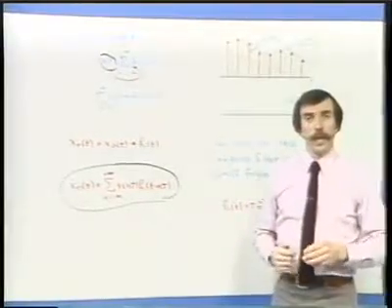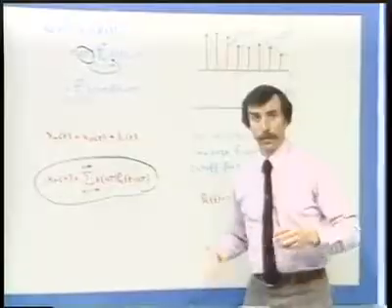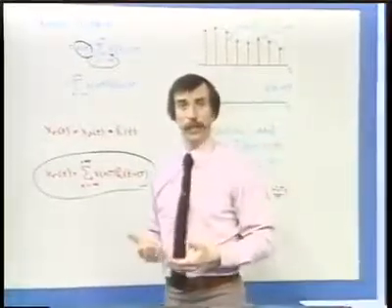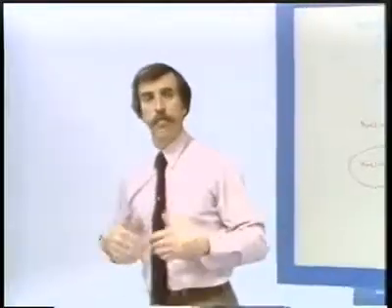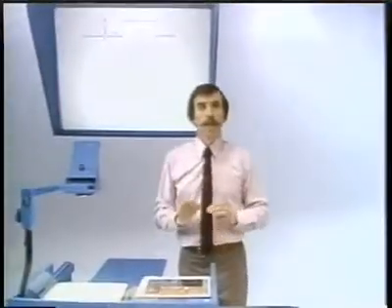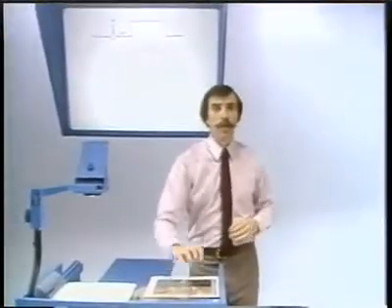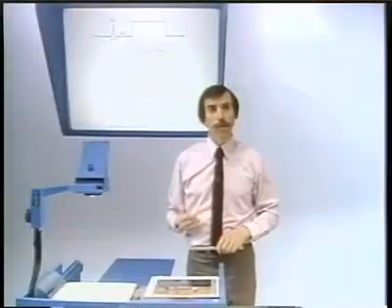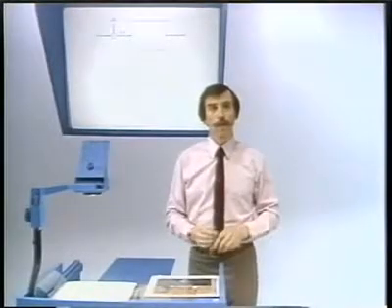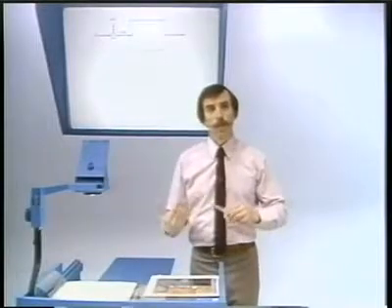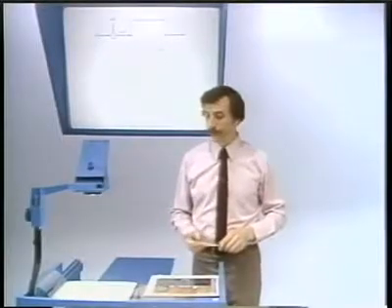Now, the kind of reconstruction that we've just talked about, and the ideal reconstruction, is often referred to as band-limited interpolation, because we're interpolating in between the samples by making the assumption that the signal is band-limited and using the impulse response for an ideal low-pass filter which has a cutoff frequency consistent with the assumed bandwidth for the signal.